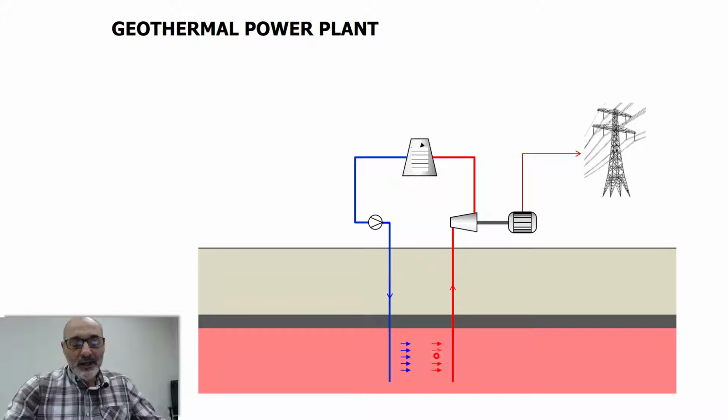This water flows to this other pipe here, and in that way it absorbs heat. So here you have high pressure, high temperature steam, then expansion in a turbine, and heat rejection to the atmosphere, and that completes the cycle. This turbine drives a generator which inserts electricity on the grid.